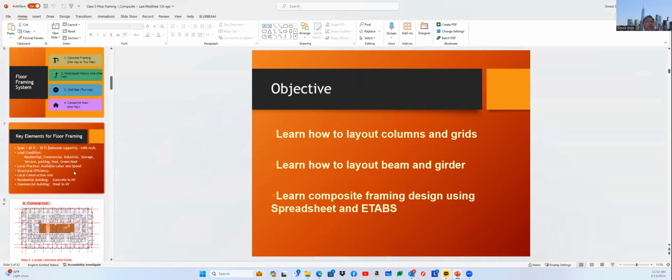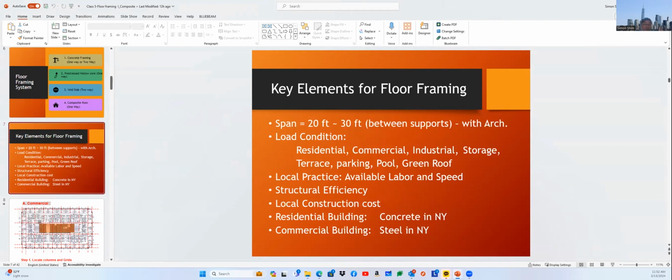So let's move on. I think it's some basic information we need to understand. Next page. Because of the office building we are designing, we need to understand the typical layout, column spacing, and beam span. It depends on your project building layout, how big that is. I didn't give you the overall size, but I expect you to do some benchmarking and come up with an existing building so that you could practice and draw the column layout more reasonably.